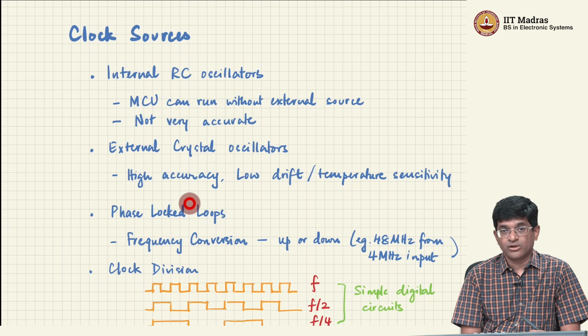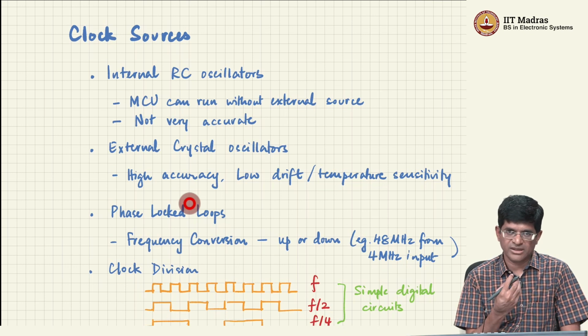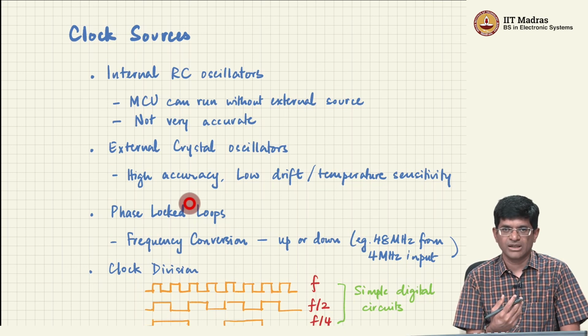Now of course comes the question of where are these clocks coming from, right, because as we already saw, we have the digital circuits which are the gates and the flip-flops, but those are elements that just exist inside the circuit itself. The only other thing that's required for them to work is a power supply, right? Whereas over here we are talking about a signal that actually explicitly needs to toggle back and forth. It needs to go from 0 to 1, 1 to 0, 0 to 1, 1 to 0, and so on, right? So we would like it to look something like a square wave.